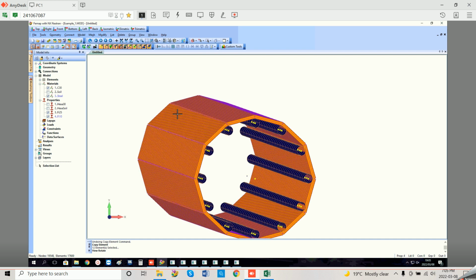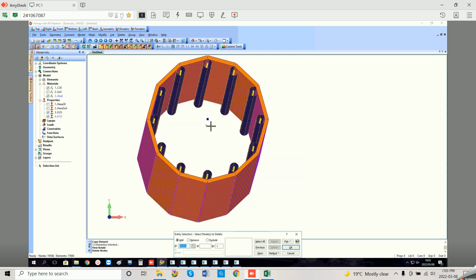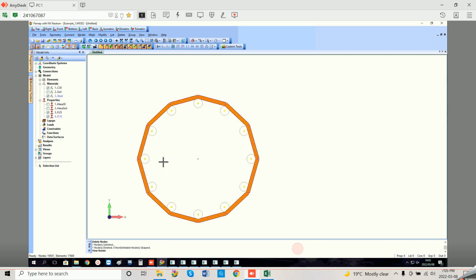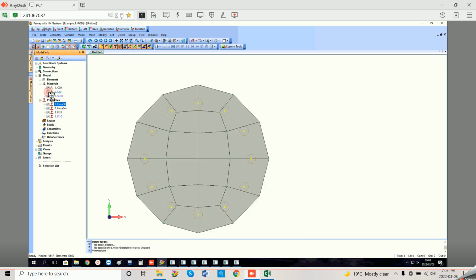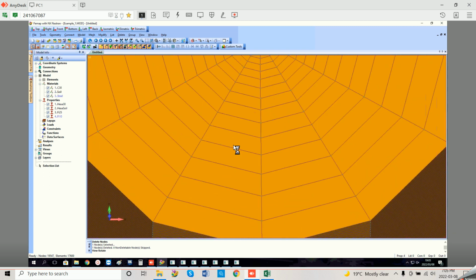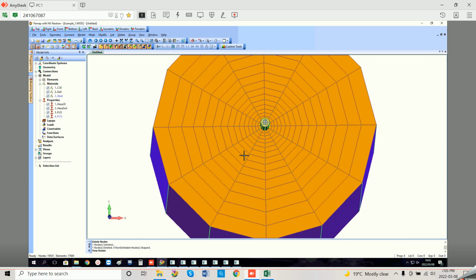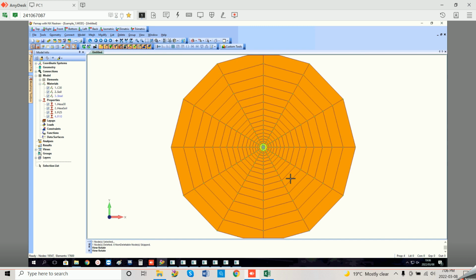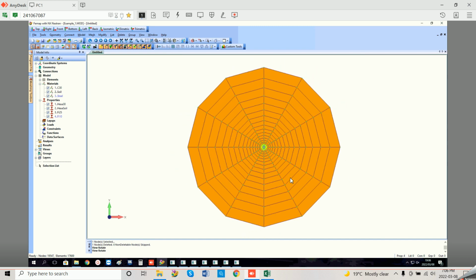Just one more thing, just make sure then you delete this node, because that was just a point we used. So now that node's gone. And yes, then that is done. So it's your stirrups done, everything else, it looks all good. So now I'm sure from now on, you just got to add boundary conditions and add loads and then renumber and coincide elements and nodes. So I can do that quickly.